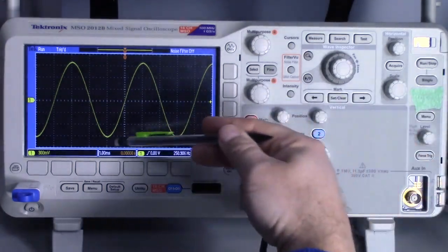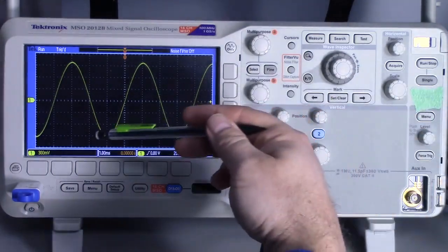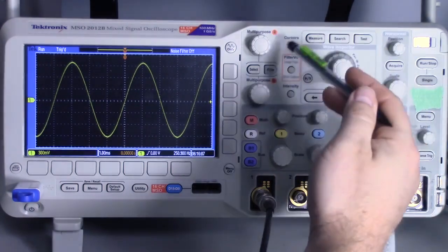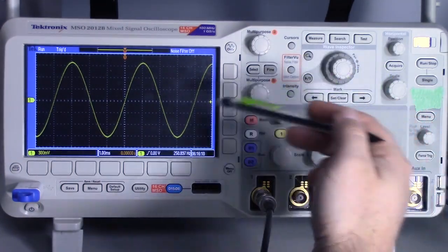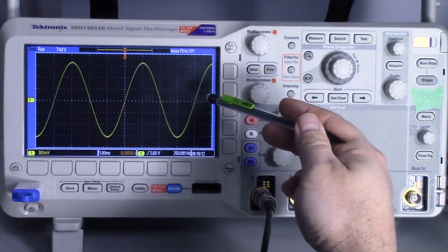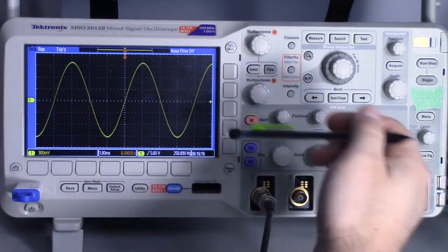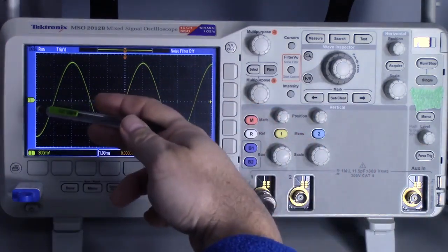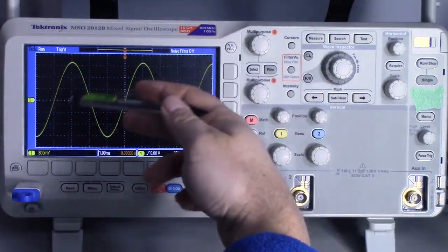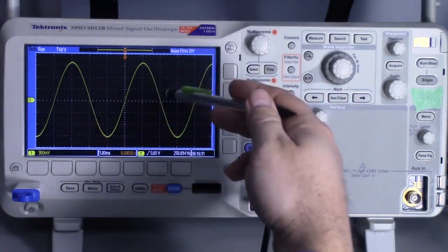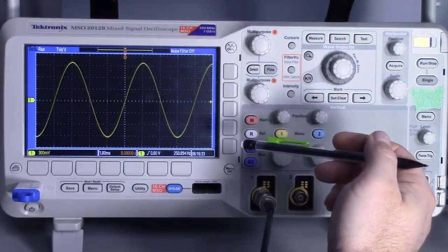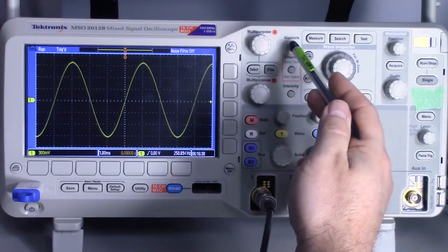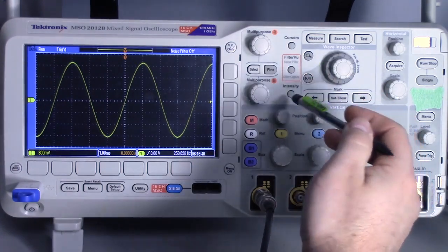But the run stop will have to do with the display. The single button will be used for capturing single triggered events. This wave inspector is very useful if you want to capture a longer period of time, but then inspect and go into greater depth. So for example, with your I2C, maybe the packet is a lot longer than what you could reasonably display, and if you display the whole thing, you wouldn't be able to get as much information off of it. So this has a lot to do with the inspection, and again, the cursors go with manual measuring.